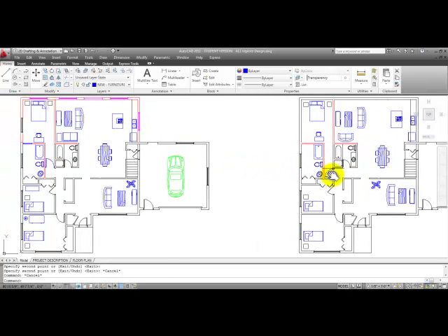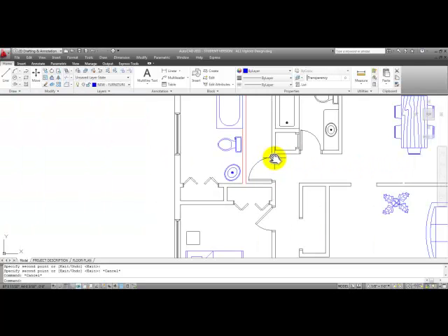Okay, we also talked about creating your own block, and that's what we're going to do with this door here. If we select the small pieces that make up this door, notice that in the Properties palette, this door was changed to white instead of ByLayer. It's good CAD practice to maintain all of these settings as ByLayer, linking those objects with the layer settings.